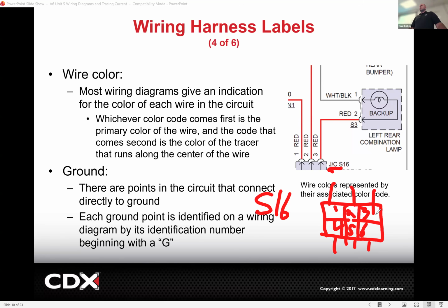Sometimes we'd have all those same wire colors come into a connector because it might be like a splice bar, a splice comb. They'll have a bunch of stuff coming together, and it'll connect into something, and that something will just be like a piece of metal that basically makes them all one circuit. You know, that's kind of common too, which is that was a giveaway by JC. It's a junction connector. It's a junction where things are coming together.